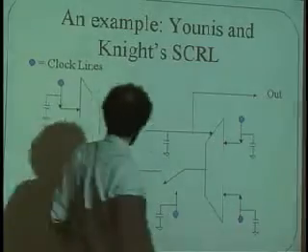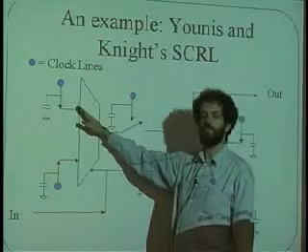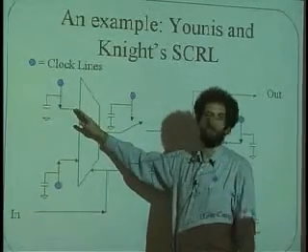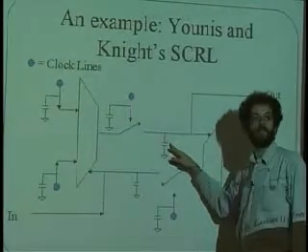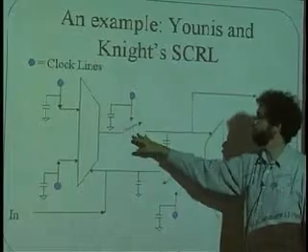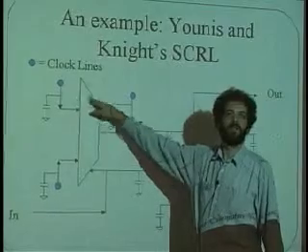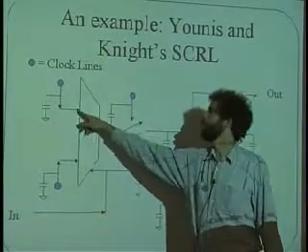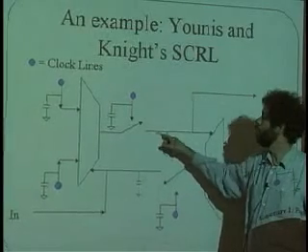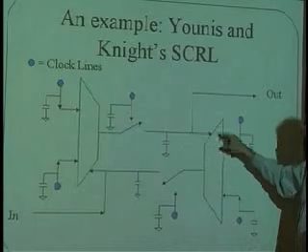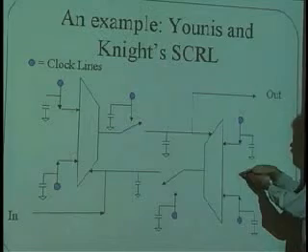And what this selector is going to do is, depending on its control input here, choose to either hook the positive power/clock line or the negative power/clock line up to a capacitor right here. And very slowly, after it closes the switch and chooses to go up here, this clock will go from low to high. It'll do it slowly enough so that the resistance along the path does not dissipate very much energy. Once that's done, that will in turn control another selector, which at a later time will go from low to high.